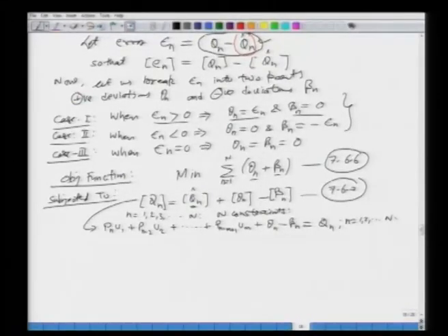So, what is this constraint doing is that it is ensuring that the unit hydrograph ordinates follow the discrete convolution process, all right. So, the unit hydrograph ordinates which we will get will be such that they will satisfy all these equations, all right. So, we are enforcing these u's to follow the discrete convolution equations, all n of them, so that we are using all the data. So, it will give you an optimal solution. So, that is one constraint.